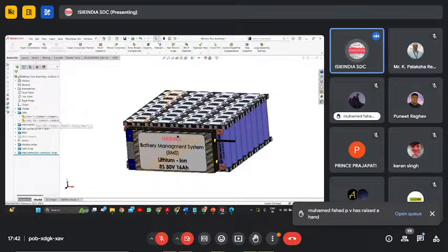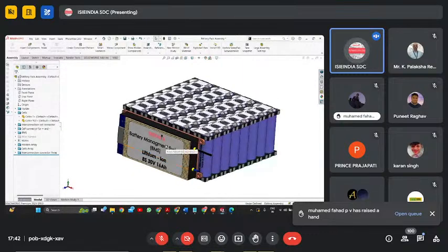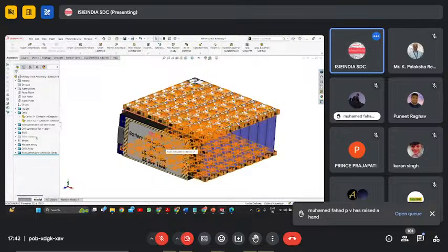After making the battery pack, we definitely use a battery management system to manage it, like the cells and the cell voltage. The BMS monitors whether there are any irregularities, over voltage or under voltage, and then it cuts the supply. In the same way, there is a CSC inside the BMS. Here as a CSC we have used a cell supervision circuit. This is a wire harness.